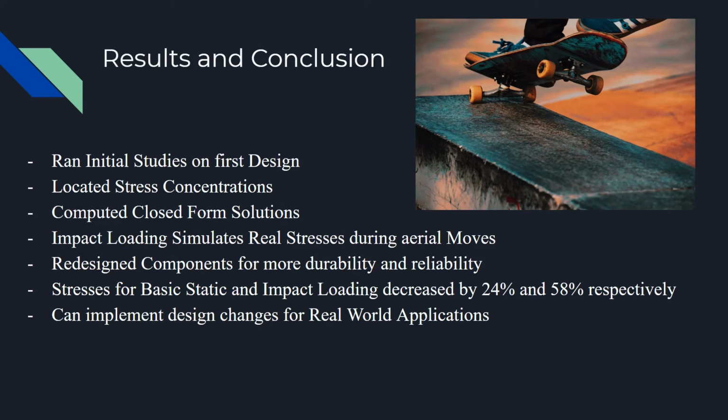In conclusion, during our project, we ran studies on the initial design to locate stress concentrations, compute closed-form solutions, and conduct impact loading analysis to simulate real stresses from aerial moves. Our design changes had real-world applications, such as durability and reliability, in mind while reducing overall stress by 24% and 58% for basic static and impact loading studies respectively.